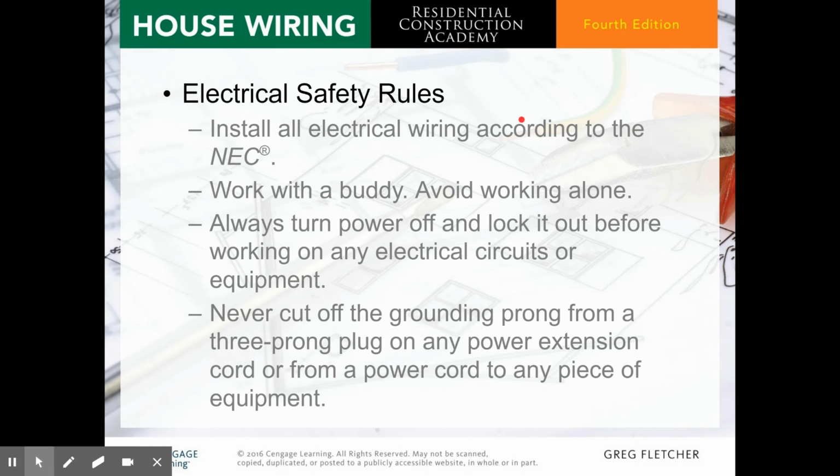Electrical safety rules. Install all electrical wiring according to the NEC. Work with a buddy. Avoid working alone. Always turn off and lock it out before working on any electrical circuits or equipment. Never cut off the grounding prong from a 3-prong plug on any power extension cord or from a power cord to any piece of equipment.